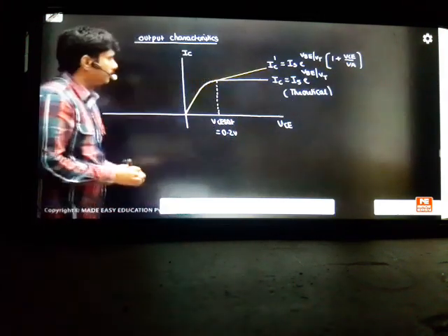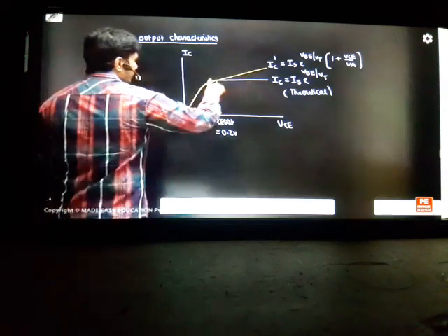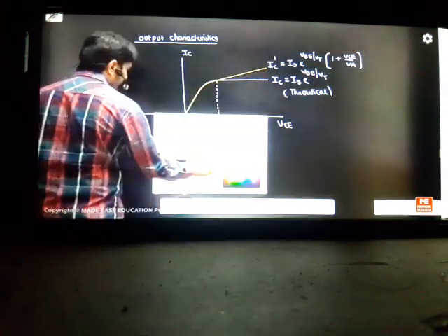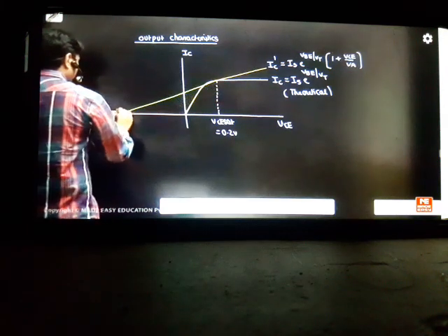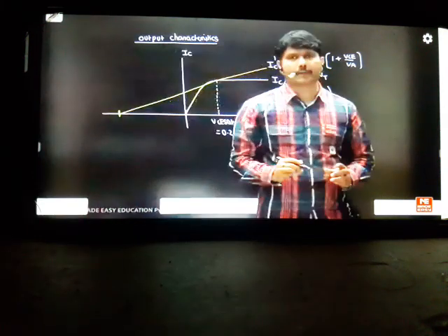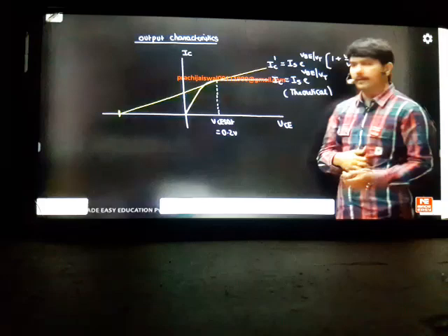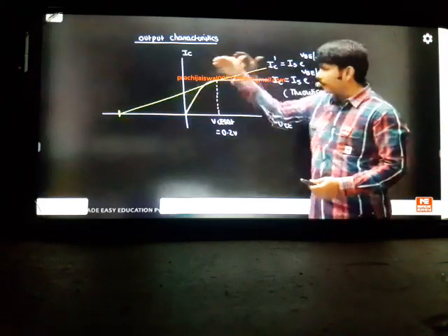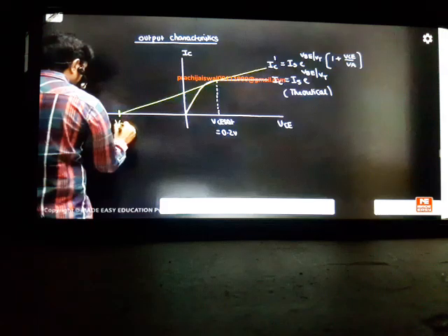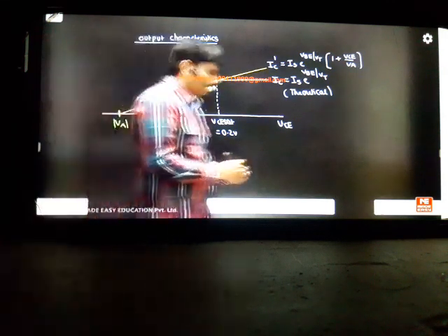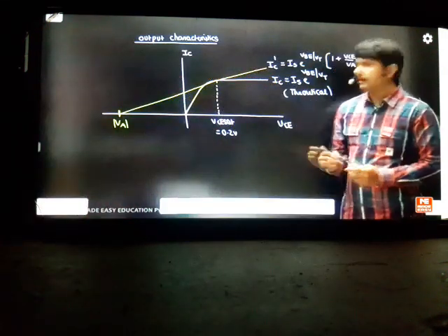What the VA signifies here is, the scientist said that every transistor will have some deviation like this, practically. So why can't you draw this line, and extend it to the second quadrant like this? Such a slope, you extend it to the second quadrant, and it will intersect somewhere in the second quadrant. Whatever the deviation for your BJT devices, definitely this deviation is there for every practical device. You just draw the sloped line into the second quadrant, and somewhere it will intersect. That voltage, he has given the name VA with modulus. That means VC, I have given the name VA on the second quadrant side.